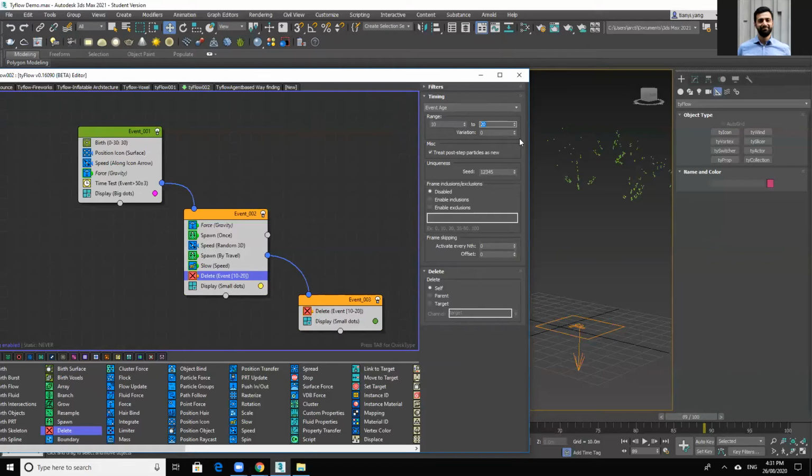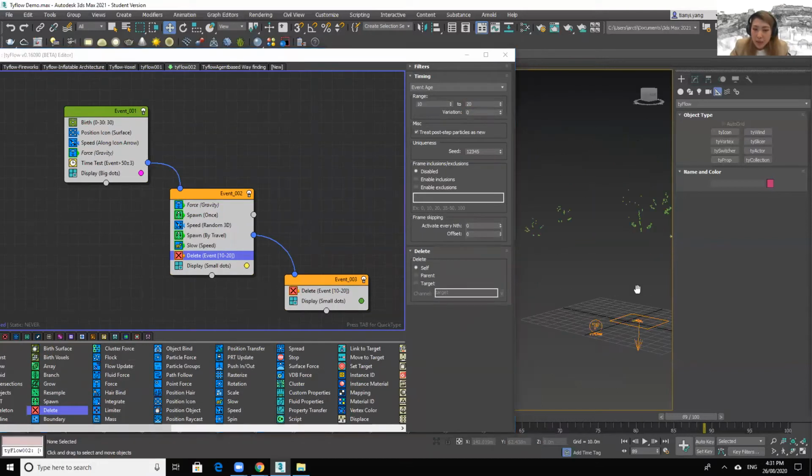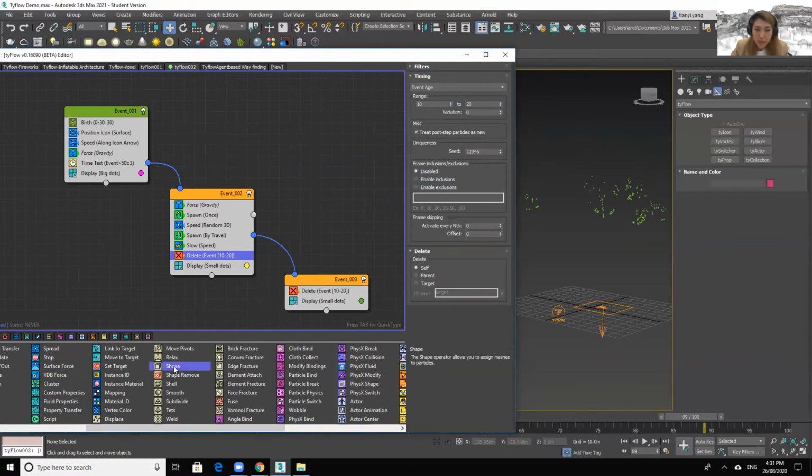Yeah. Okay, cool. And then the other question was, if I want to change my particles to teapots exploding, how do I do that again? Sorry, what? If I wanted to change the particles to teapots, how do you do that again? Wasn't it within display? I forgot. Yes, so by changing it to customize the shape, we need to add one more thing called shape. Oh, that's right. To give it a shape.